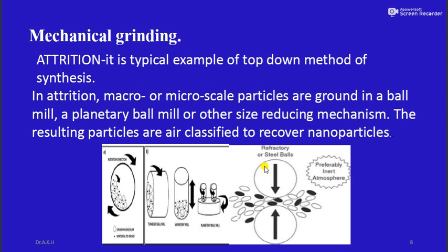The major advantage is the possibility for easy scaling up to tonnage quantities of the material for various applications. And here you are going to have contamination from milling media or atmosphere, and the need to consolidate the powder product without causing the loss of nanocrystalline microstructure. Mechanical milling is achieved using high energy shaker, tumble mill, planetary milling.